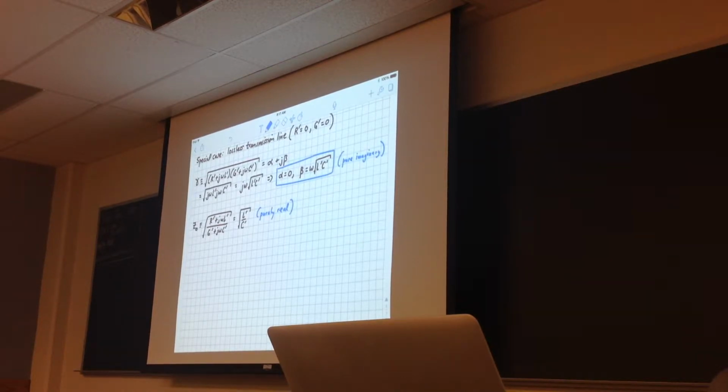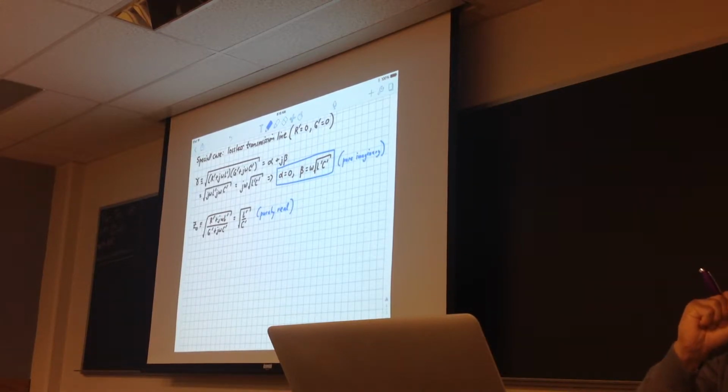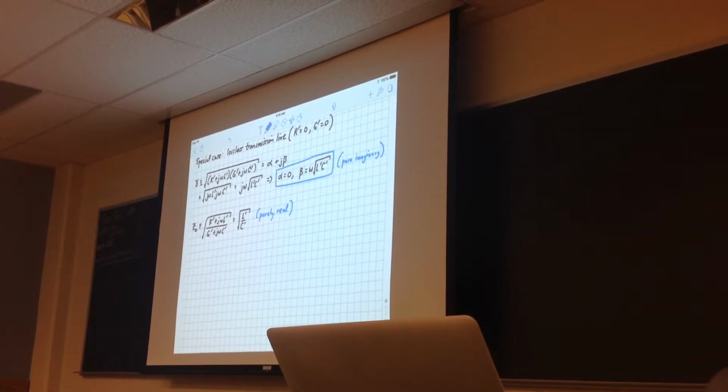So you'll see 50 ohms is pretty typical, and so is 75 ohms. They're a little bit different. The 75 ohm coaxial cable will be a little bit more narrow, and we're going to see later, when we derive inductance per unit length and capacitance per unit length, that the geometrical parameters of the coaxial transmission line are important for determining its transmission line parameters and therefore its characteristic impedance.